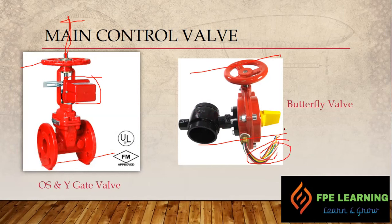And how are you going to identify its position? This is an indicating type butterfly valve. Indicating means we have a yellow flapper here, right? Normally, this is our pipe, right, and the flapper is now perpendicular to the pipe. If it is perpendicular to the pipe, it means the valve is closed. If it is parallel to the pipe, something like this, it means the valve is open. At this moment it is closed.